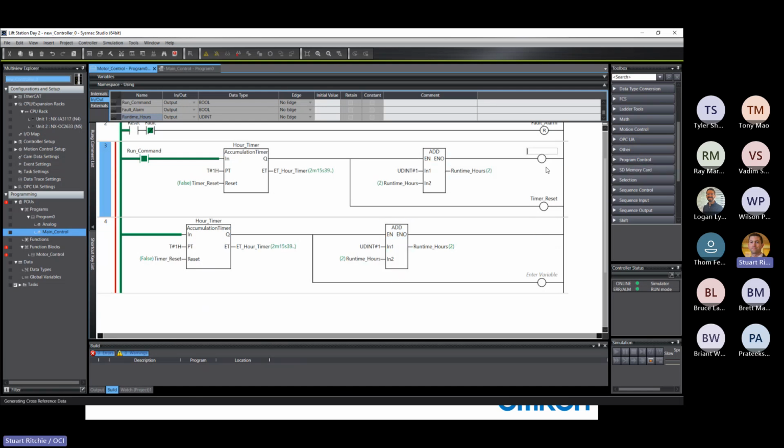If you try to do the paralleling like you normally do with a function or a function block, it doesn't always branch it. So I generally lay it out with outputs first, and then I insert the other output instructions that are Boolean.